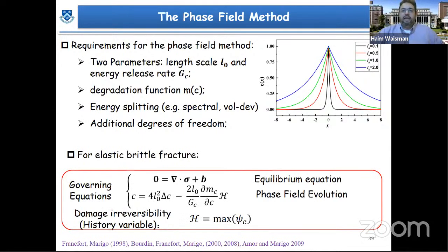Right, so for elastic brittle fracture, in order to introduce phase field, you now need to solve a coupled set of equations. The first one is just the standard equilibrium problem. And then the second one is the phase field evolution equation that comprises again of two terms, the diffusive term described here by this Laplacian and the length scale L0, and the source term which drives the fracture and propagates that.